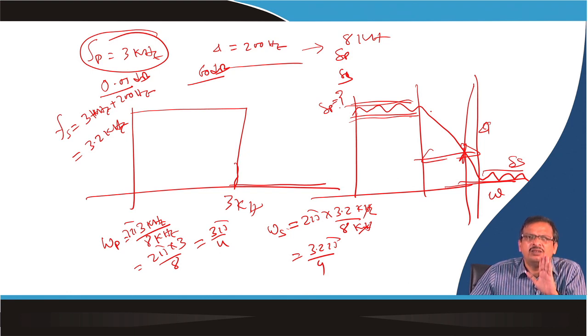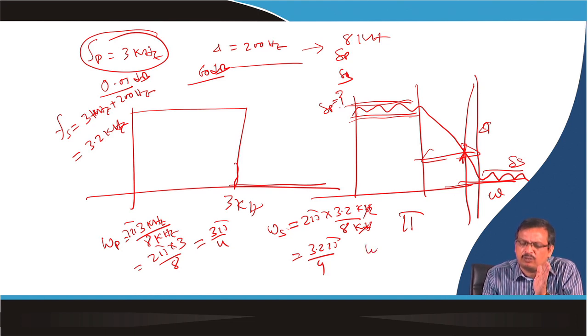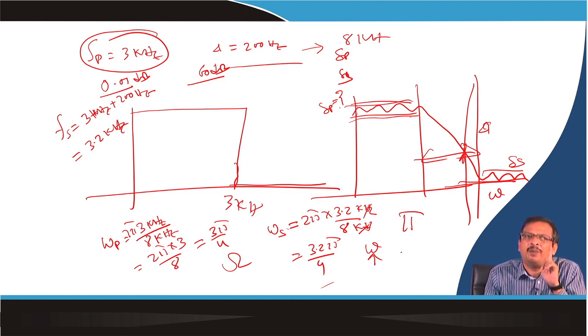So the hertz to omega conversion gives the normalized discrete frequency. When I say the discrete domain, why is the maximum frequency pi? Because it is pi radian per sample, not radian per second. That's why we write it in small omega. When I say analog frequency, we write it in the capital omega. This is radian per second and this is radian per sample. That's why we divide by Fs, F by Fs.